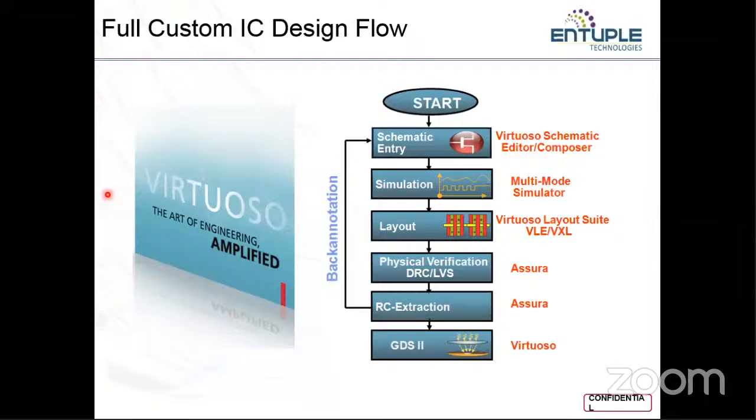If you find some devices left out or some interconnections missing, you can go back, redo it, save it, and then come again for DRC and LVS. Once your design is DRC and LVS clean, you'll move into the next step, which is called parasitic extraction. We call it RCX, or RC extraction.